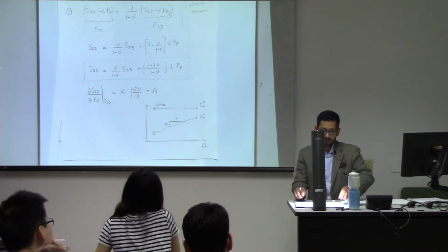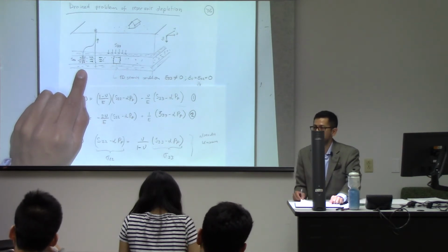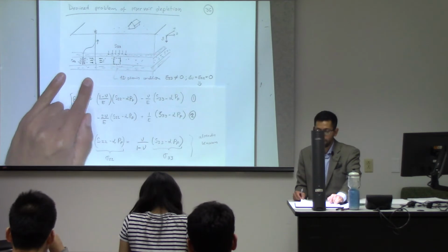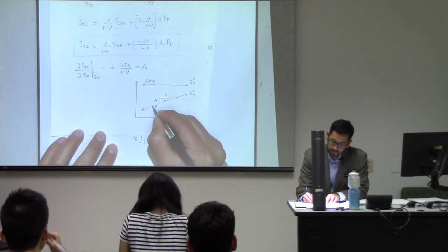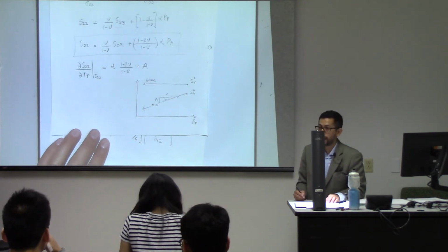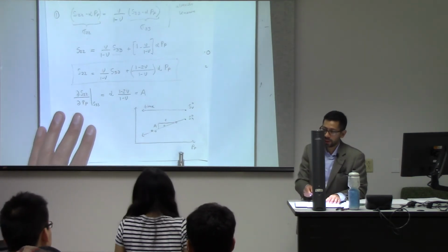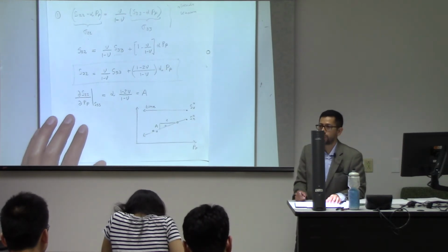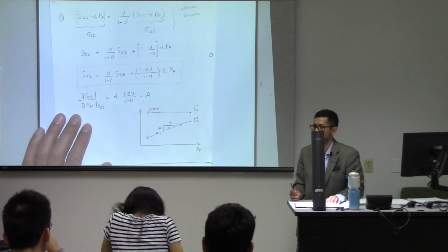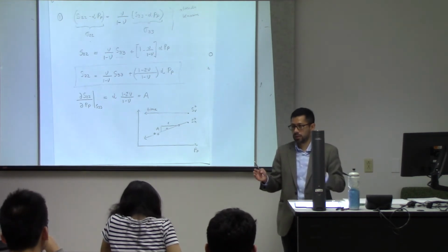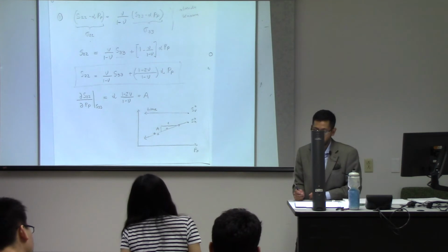And if we come back to the field, as you deplete, you could also measure horizontal stress. And actually, there are many measurements and many cases that have documented how this total horizontal stress decreases with time, because that's a value that you can actually measure. So apparently now we know how to calculate that decrease in total horizontal stress. Remember that effective stress, though, is always going to increase. The total horizontal stress, because it has the pressure component, decreases. But the effective stress is always going to increase. And we're going to plot that in a bit in terms of the Mohr circle.